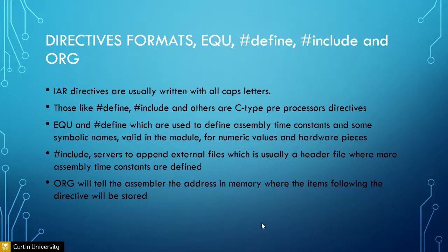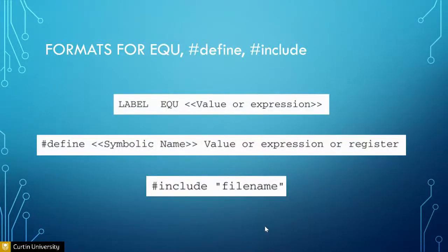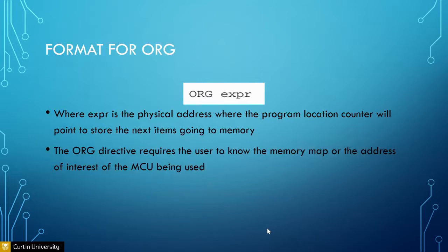There are a couple of directives that are important for the user to code: define, include. Just now we defined delay as 50,000, so it's very easy to understand. Delay is basically a number of 50,000. If you want to make it faster, you divide by 4, and so on. When you define the value as something, it's easy to understand the code. So this is the format. H include, you include the library and so on. Without all this, your code can still work. In fact, when you compile it, it will be exactly the same machine language hex file, but this allows you to understand the code and write it in a much better way.